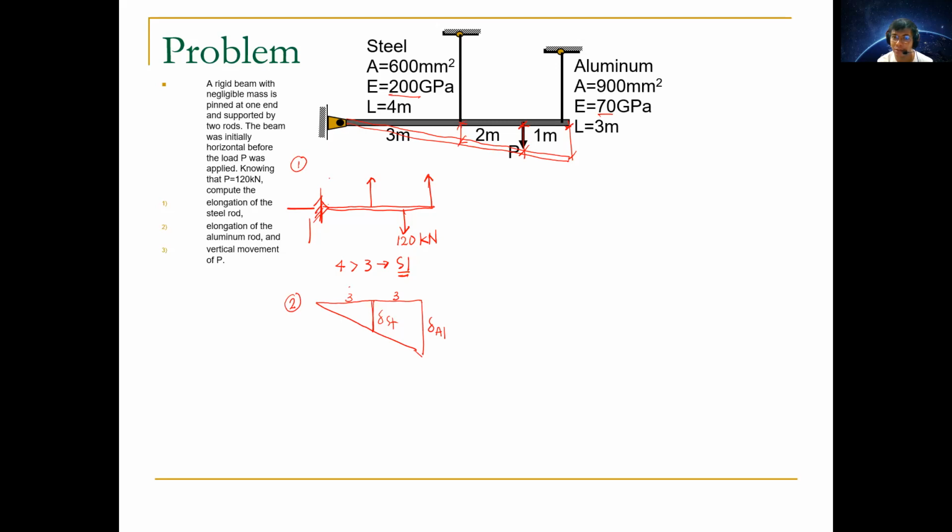But for strain equations, since we tend to ignore those topics, after getting the equilibrium equations we tend to get lost in the calculations on what to do next because we don't know which formula to use. So that's why we have to force our brain that after knowing that it's statically indeterminate, we look for strain equations first, the compatibility equations, those deflection formulas.